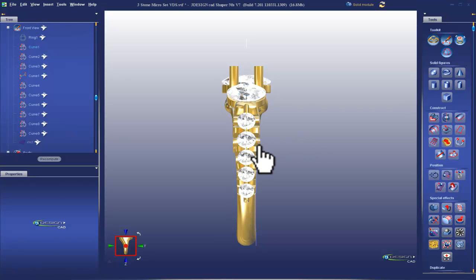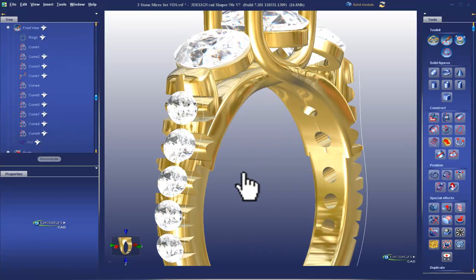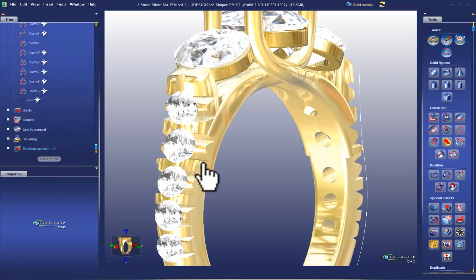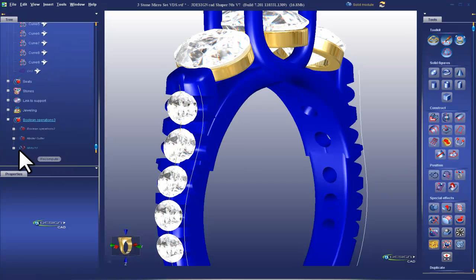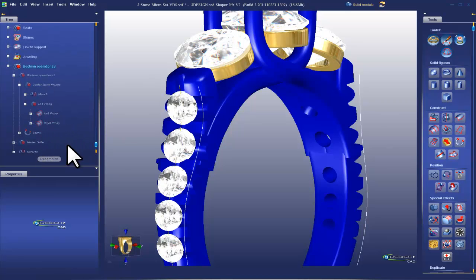There is one issue that I see, but it's not from the shank, it's from the cross-section of the loft. And to fix that, I just need to find my loft. It will fix both of them. It will be under here, and center prong, left prong, and there are my lofts right there, left and right prong. And you see by naming them all, I can really find exactly where I want to be.